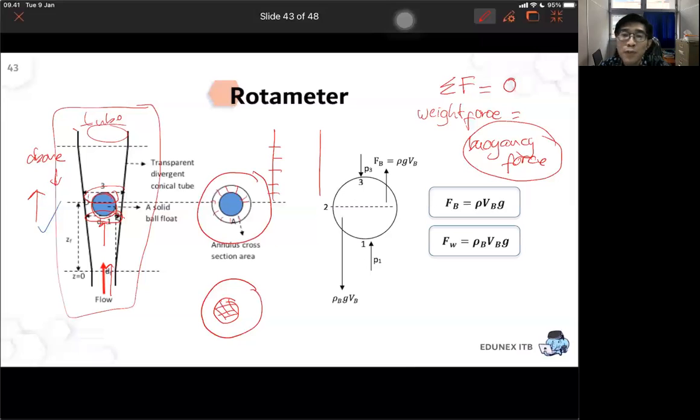Basically, if you see from our discussion last time about the Venturi meters and then orifice meters of the pitot tube, basically how to calculate the velocity of the fluid is by creating the pressure difference, right? At 2 points at the pitot tube, and then in the pitot tube, you calculate the pressure difference between the outside condition with inside the tube.